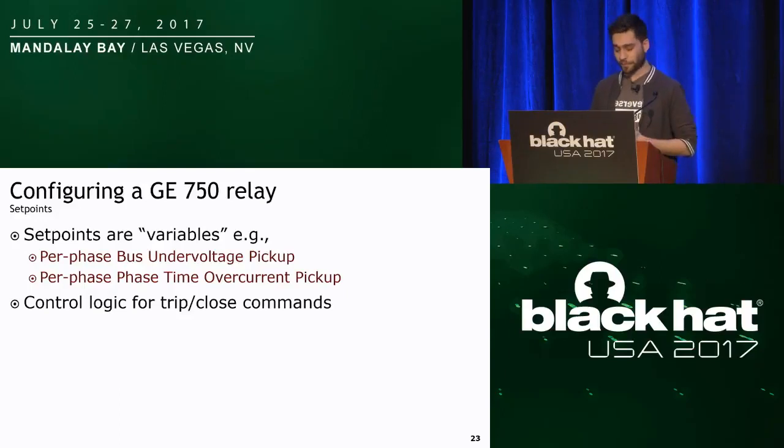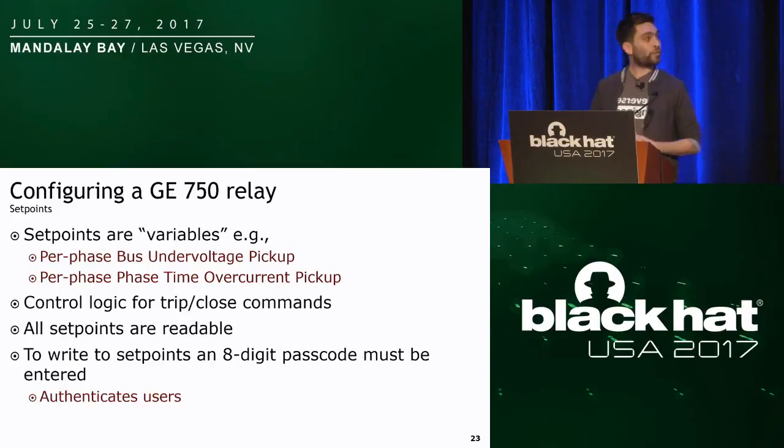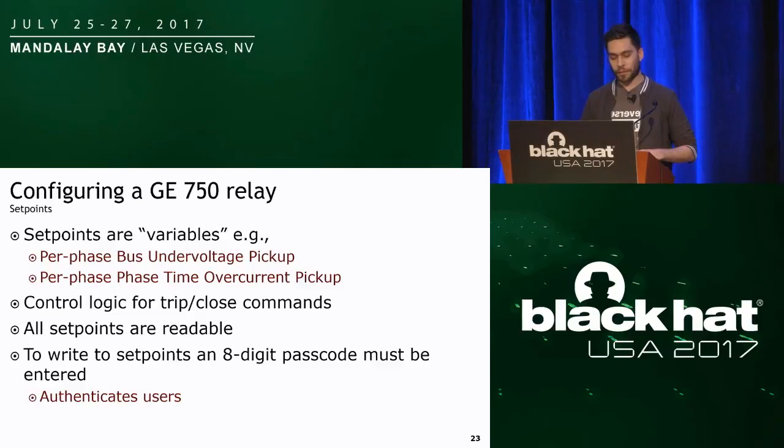Now, in terms of access to these set points, they are all readable by anyone, any unauthenticated user that has access to the device, either physically or remotely. However, if you want to write back to these set points, if you want to modify the values they contain, you need to provide an 8-digit passcode that essentially authenticates users.